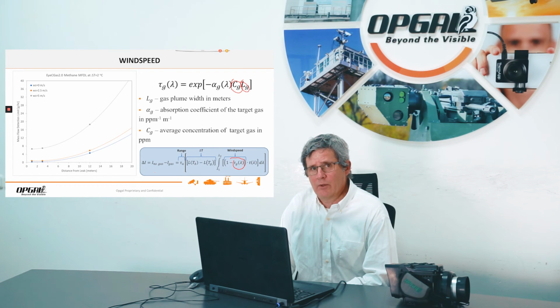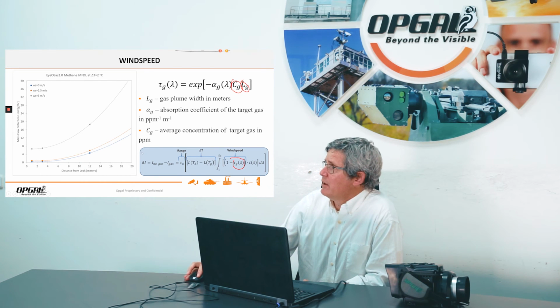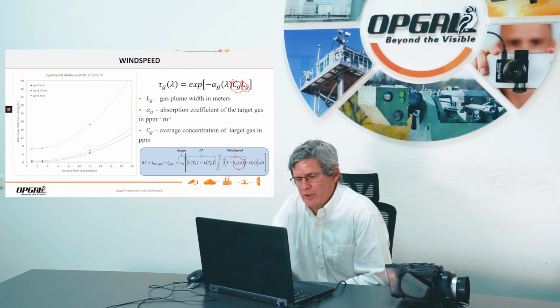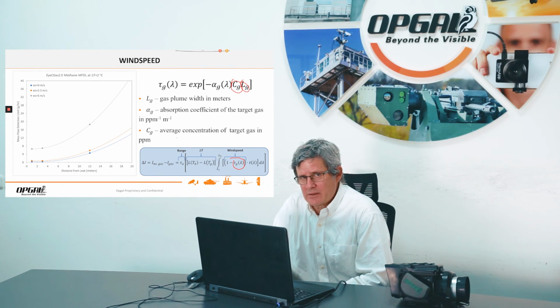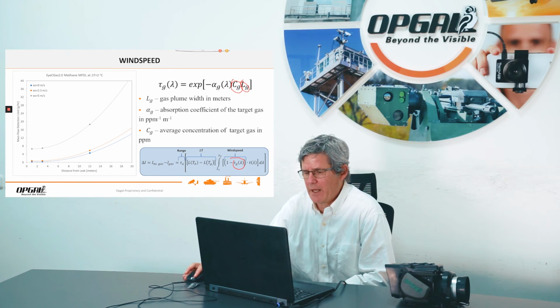And looking at this OGI camera specific OGI equation, every time we define a mass flow detection limit in mass per unit time, we have to state what is the temperature difference and what is the settings, if it's indoors, outdoors, what was the wind speed, and what is the range, what is the distance to the leak from the camera.